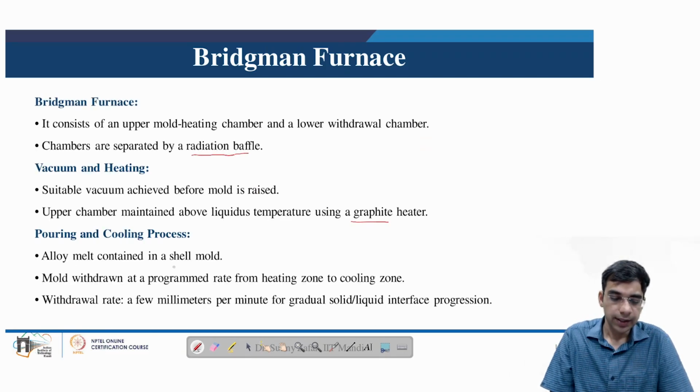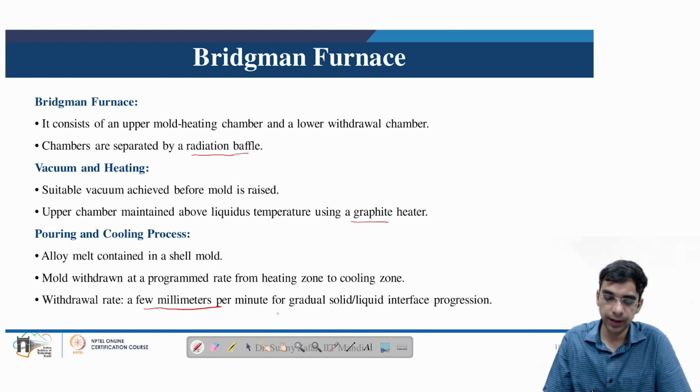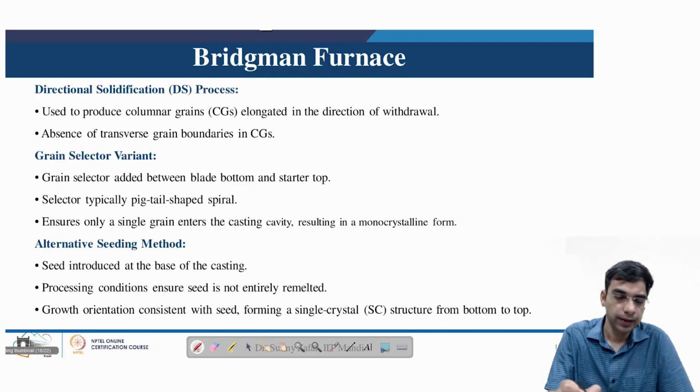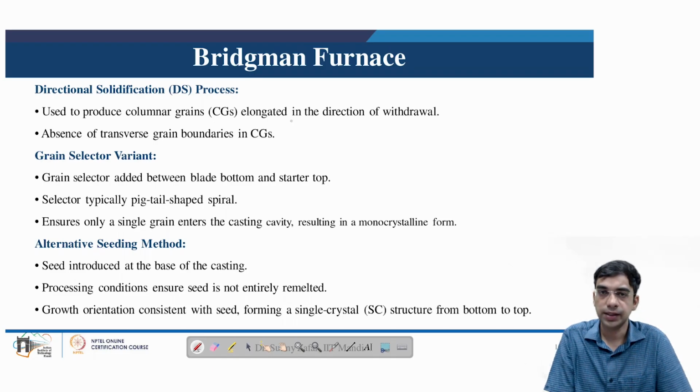and alloy is contained in the shell mold, and mold withdrawal rate, as I just mentioned, is programmed such that from the heating to cooling zone it is done at a few millimeters per minute, allowing a gradual solid liquid interface, which will result in a single crystal grain via the grain selector. So directional solidification is possible to develop columnar grains elongated in the direction of withdrawal. So there is an absence of transverse grains in the case of directionally solidified grains.